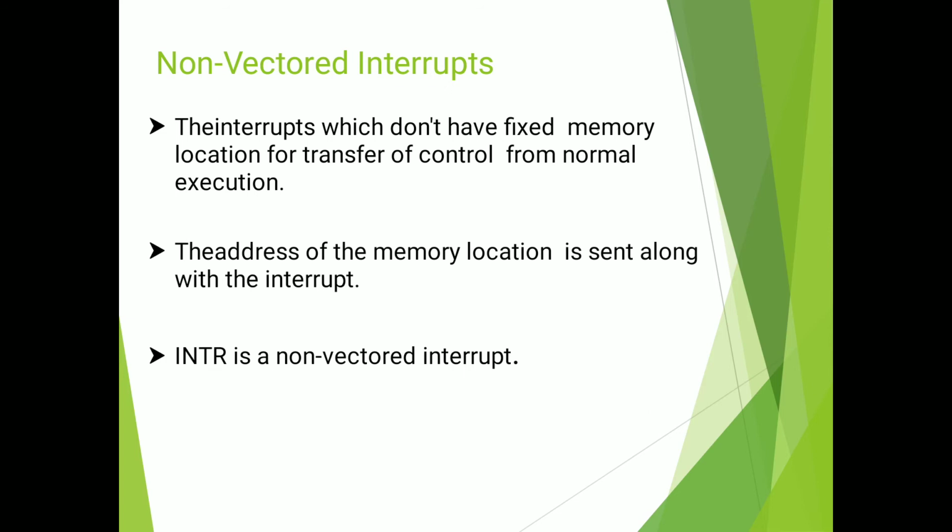Non-vector interrupt. The interrupts which don't have a fixed memory location for transfer of control from normal execution. The address of the memory location is sent along with the interrupt. That means they have no fixed memory location. It is called a non-vector interrupt. INTR is a non-vector interrupt.